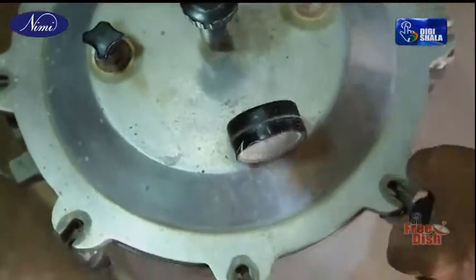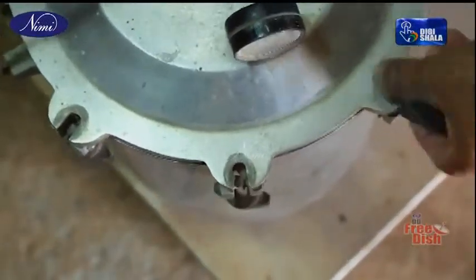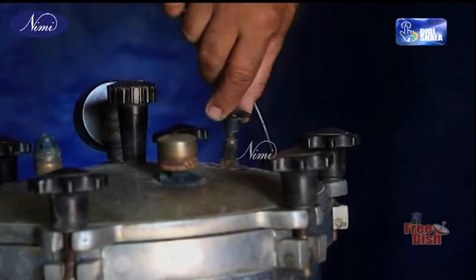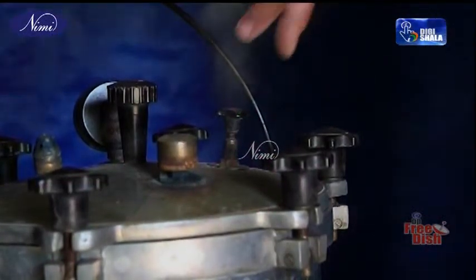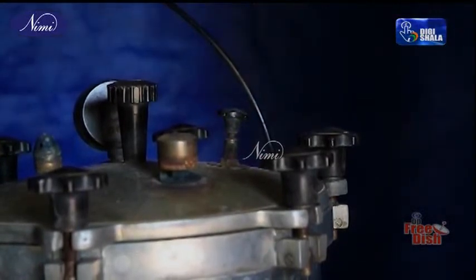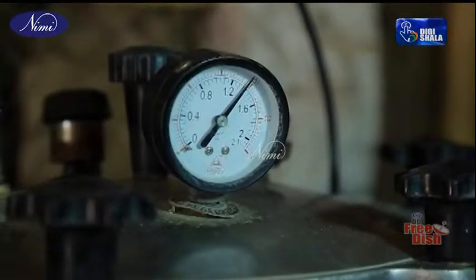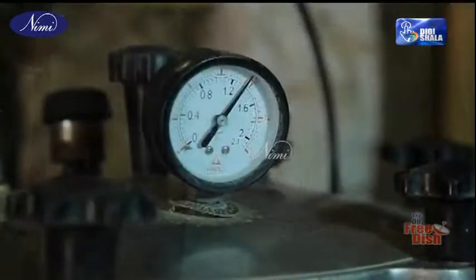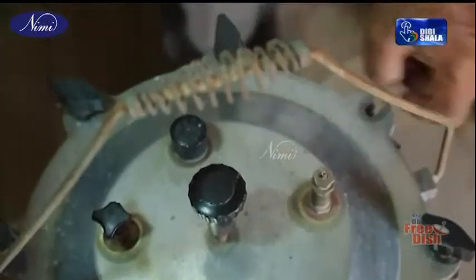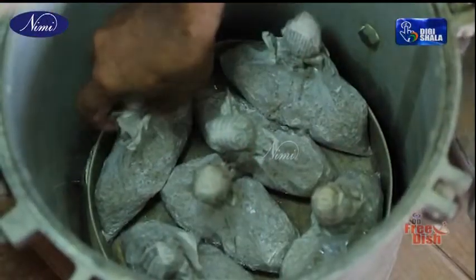Close the top lid by tightening the knobs or bolts given at the top. Open air outlet and allow the air to come out. The air outlet should be closed immediately on noticing the escape of steam with the hissing noise. Allow the pressure to build up and maintain the required pressure for a required period. Switch off the power and allow the equipment to cool. Gently open the lid and take the sterilized material out for further use.